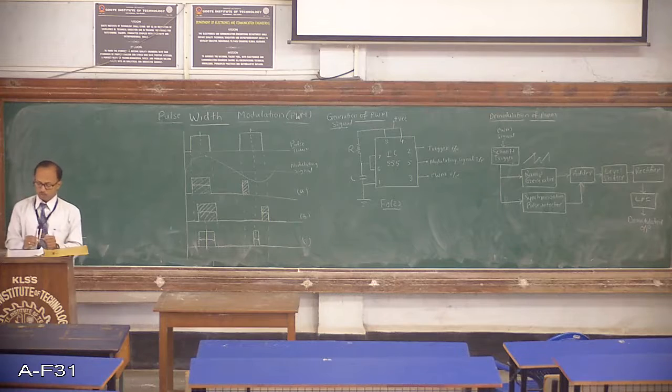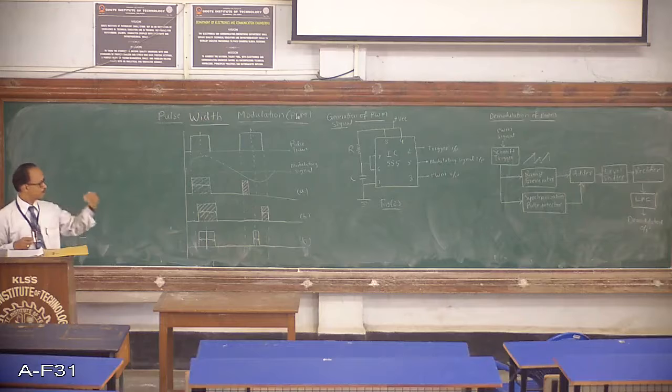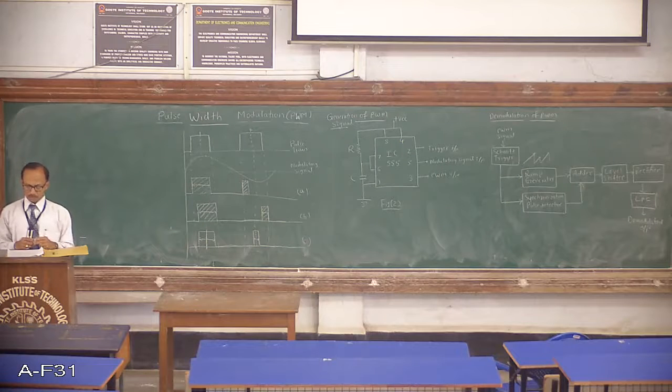Here the negative offset shifts the waveform down, which is clipped off with the rectifier. The job of the level shifter is to shift the whole waveform after the adder down. Because of the negative offset voltage, the whole waveform will be shifted down, and then the rectifier, as you know, just clips off the negative portion of the waveform and produces the positive portion, that is, it produces a kind of DC output, isn't it? So that is what this rectifier does here also. It just clips off the negative portion of the waveform.